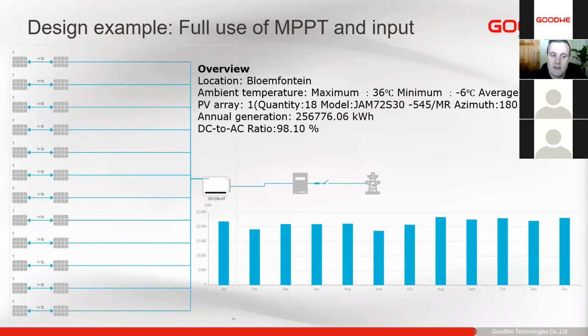That gives us a total of 98.1% DC coverage, so about 111.7 kilowatts on the inverter itself. So not a full 120, and obviously we won't get that 10% extra. But sometimes the site only requires so much. For this one, we could have used the 110 or even a 100 kilowatt inverter, which would have been sufficient.